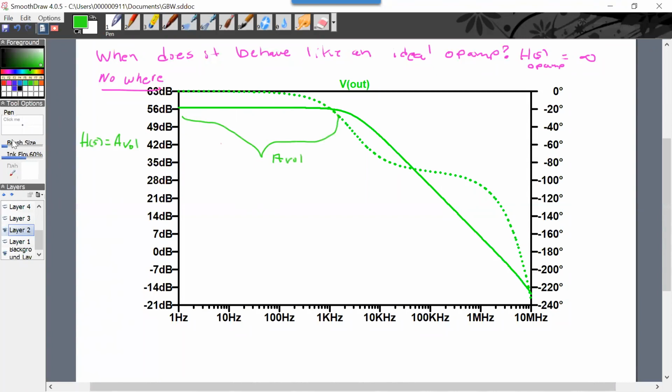All right. Now, where is it acting like an integrator? Well, if you have a constant divided by s, that's an integrator. And we can see that in this range, the phase is very close to minus 90, right? Because that's j omega, which has a phase of 90, but it's in the denominator, so the phase turns negative when we bring it up into the numerator. So in fact, now the phase does start to dip in here. There's more going on in this op amp. So really, between here and here, it's acting like an ideal integrator.